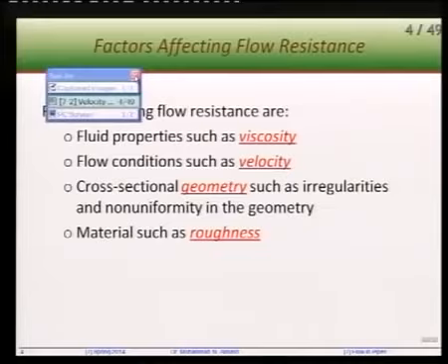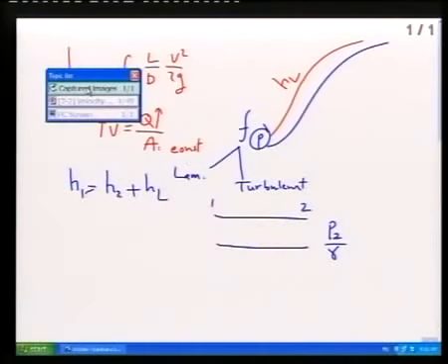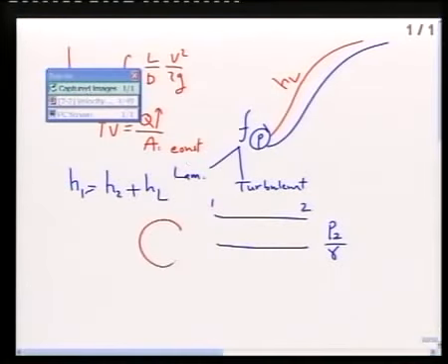If you look at this, for example, this is a circular pipe, and we can imagine a pipe that has this cross section. Both have the same area, by the way, but I would expect that this might have less head loss than this, because we have here corner edges, rough edges, and this might really create eddies and so on.